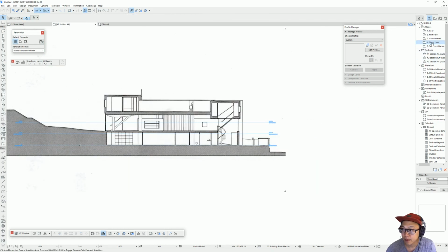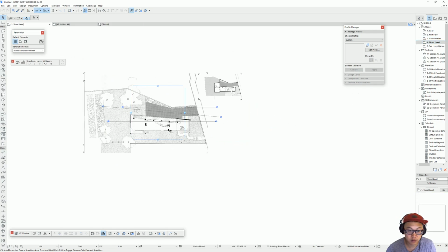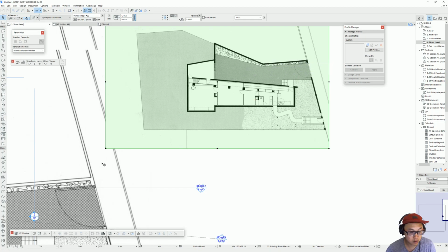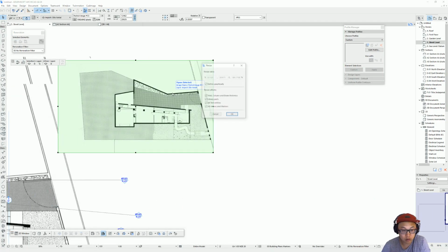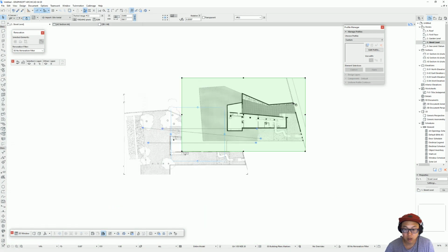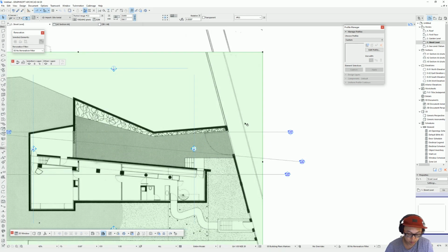And we go to garden level. Oops, where's the plan? The plan is on street level. This is going to be resized, and we can just quickly measure this wall. So I'll press M to get the measure tool. So it's about 11.8, and I'm just going to take that and resize, and 11.8. Just gonna try to superimpose it, make a copy.